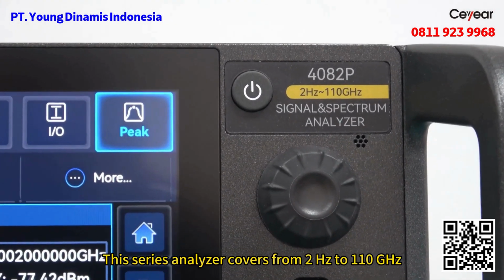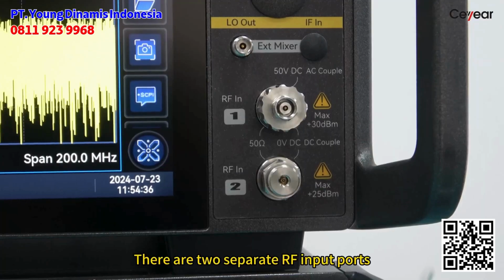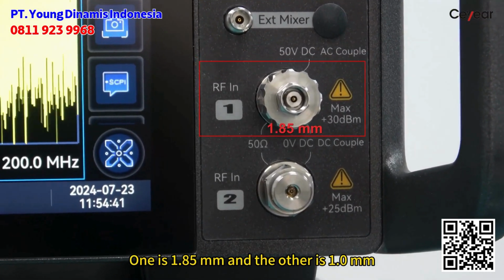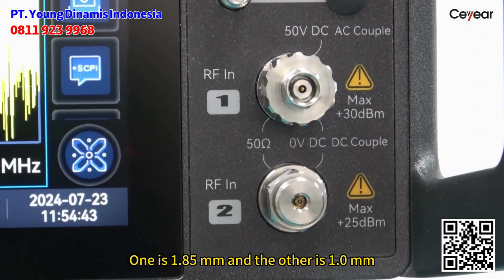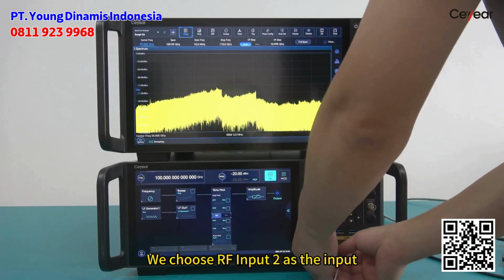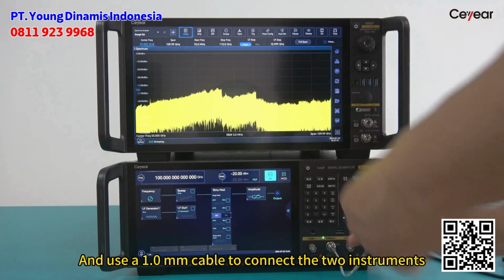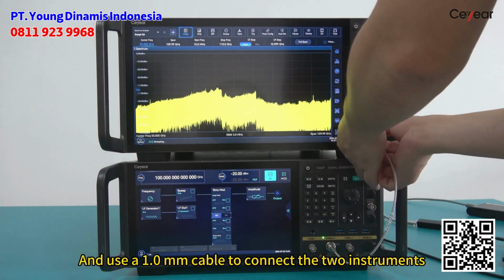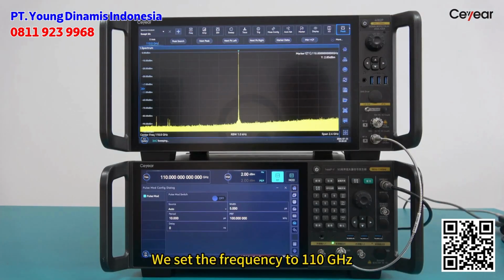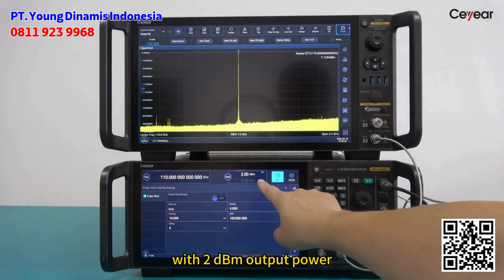This signal analyzer covers from 2 Hz to 110 GHz. There are 2 separate RF input ports. One is 1.85 mm and the other is 1.0 mm. We choose RF input 2 as the input and use a 1.0 mm cable to connect the 2 instruments. We set the frequency to 110 GHz with 2 dBm output power.